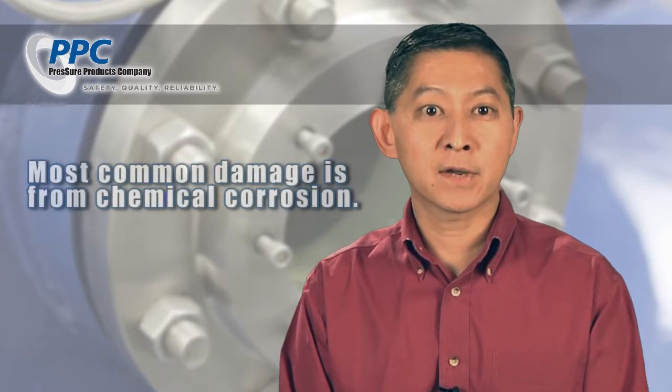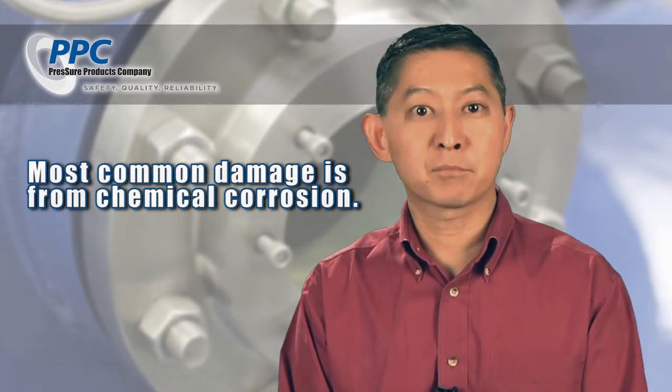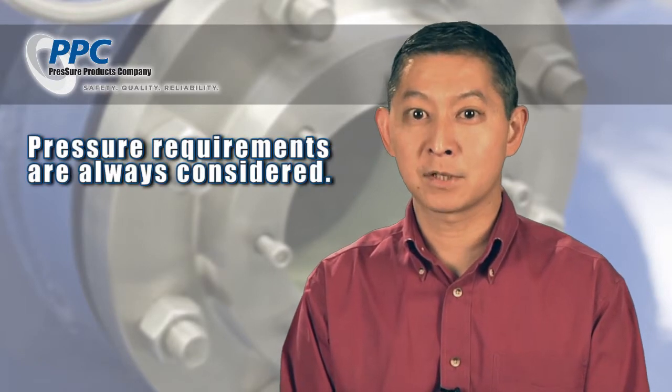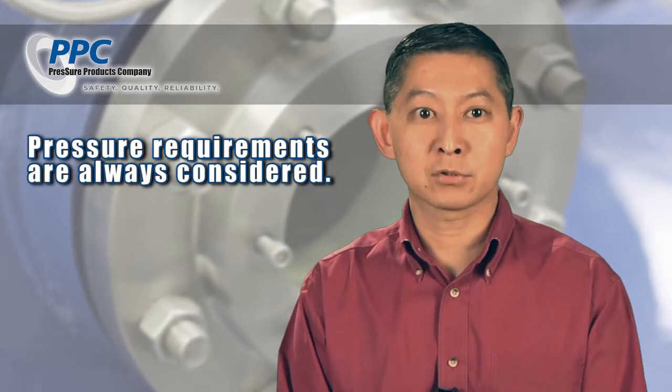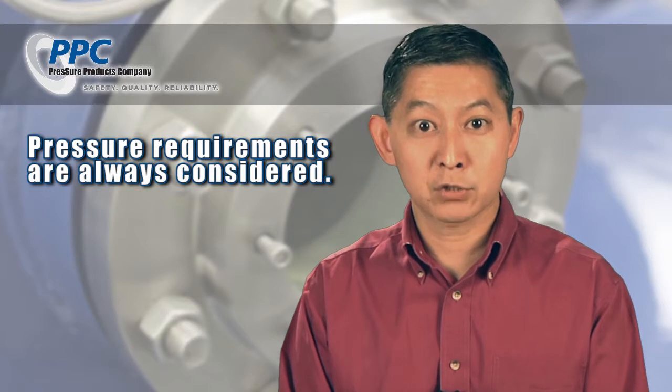I mentioned in the previous segment that mechanical damage-induced failures are very rare. In my view, the biggest reason for this rarity of pressure-induced failures is that this mode of failure is easy for people to understand. If the contraption you want to put your side window on is pressurized, the side window itself must be able to take the pressure and more. That's obvious, so everyone explicitly calls for the right pressure, and that's also why safety margins are specified for pressures.